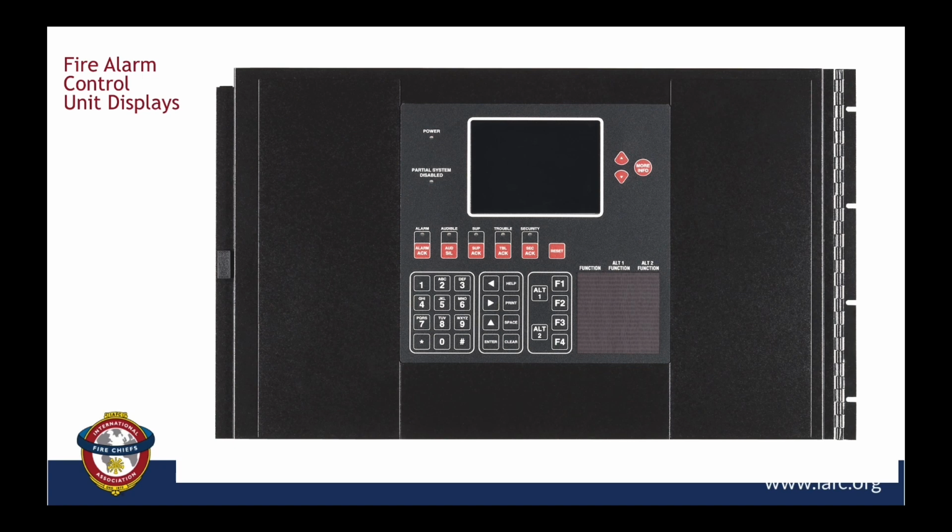So now you've gone back to the addressable, analog type systems. But once again, take a look at the similarities. We have a power on light up here at the upper left. This particular one gives you a light in case you have a system that's partially disabled. It's normally a trouble condition. It gives you also a disabled, partially disabled light. But when you go across here, it's the same stuff. Alarm acknowledge, the different acknowledgements and the different resets that are all accordingly set up here, along with the trouble lights, the supervisory lights.